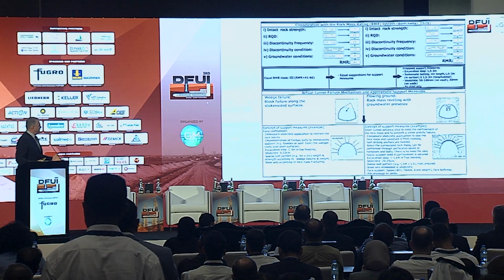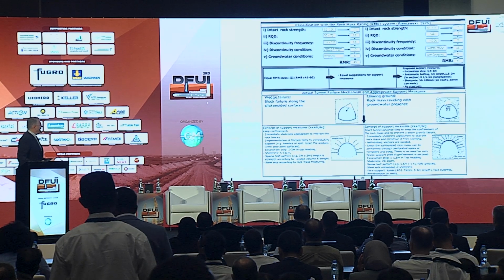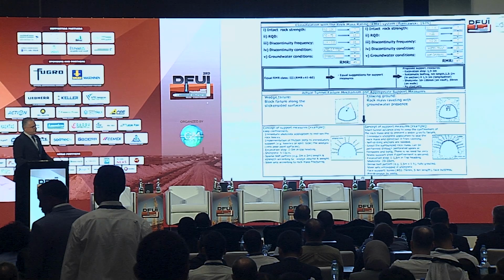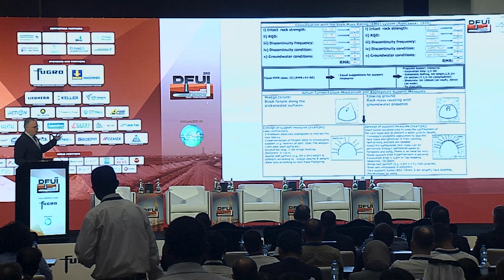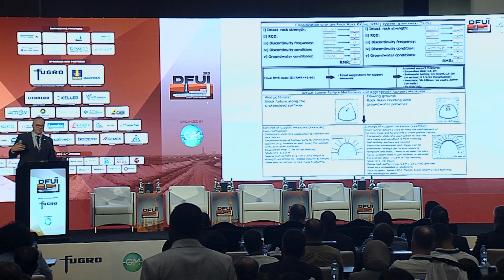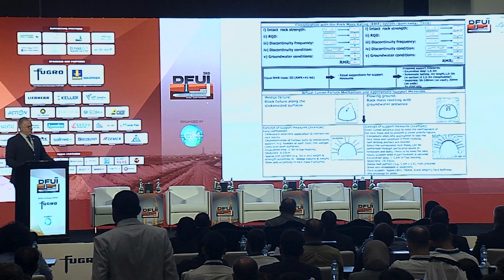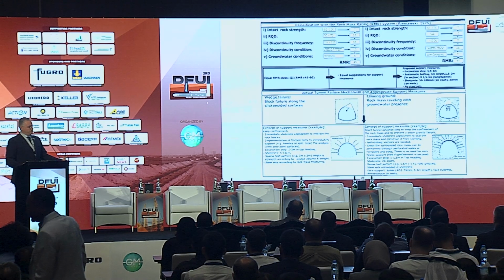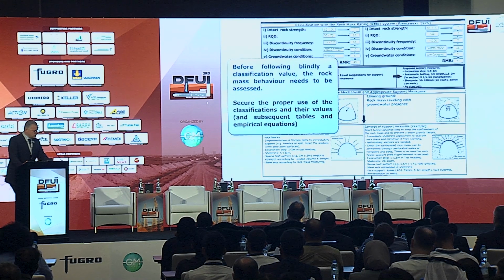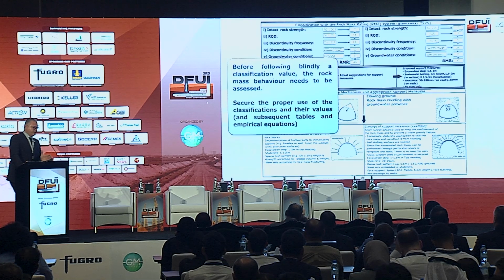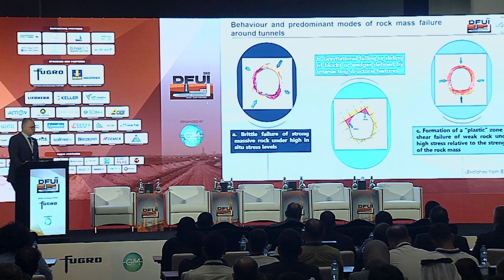On the one hand, you have to retain and keep the confinement, and of course, implement friction bolts in one case. On the other hand, you need to pre-support with some spiling or with your tunnel excavation step. So before following blindly any rock mass classification, we need to assess this rock mass behavior.